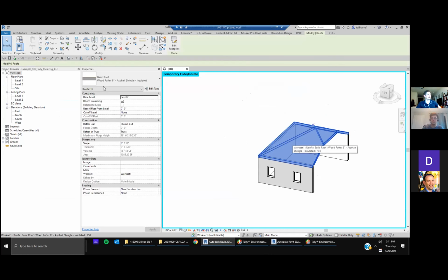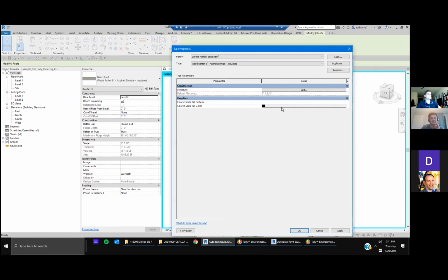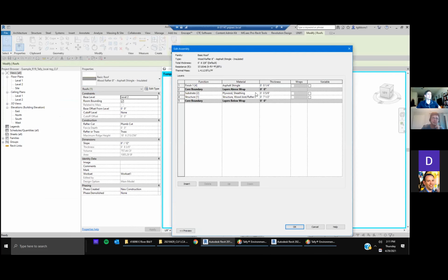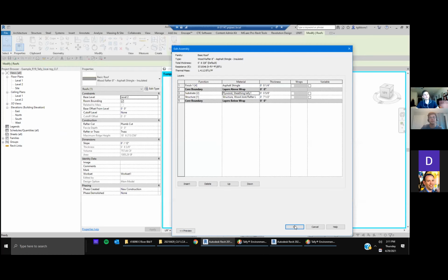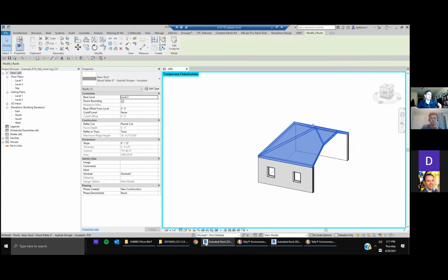And design options. If you're noticing something wrong in Tally, you can go in and edit it. If you wanted to rename this plywood sheathing Tally 1, just to remind myself, oh, that's the roof plywood sheathing Tally 1, which is different from the sheathing somewhere else, which is Tally 2, and I found that by doing the hide isolate.